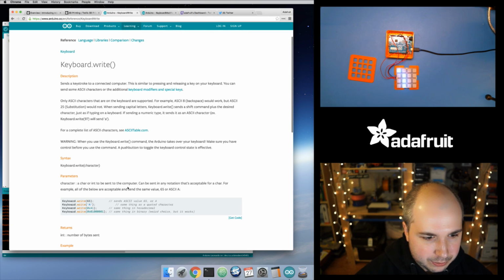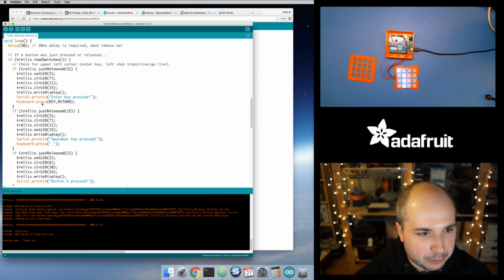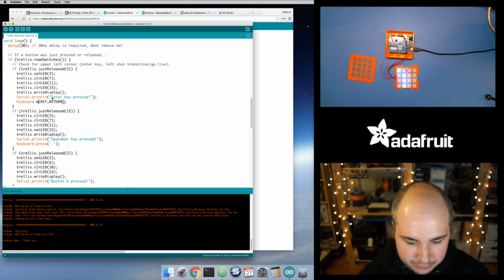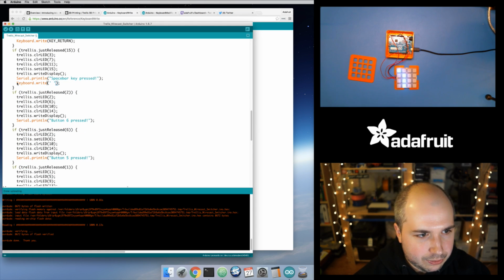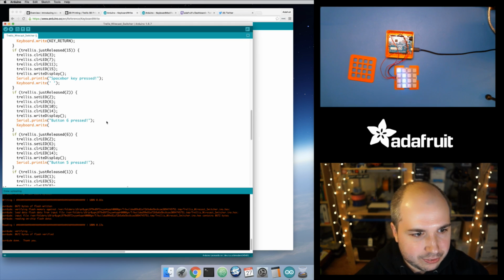Okay, so let's try this then. Let's do keyboard.write instead of keyboard.press. So let's do keyboard.press return. Let's do keyboard.write, and let's do keyboard.write for this. And let's go in and do this for all of these. Then to test this, I'll open up a text editor. Because I'm only using number keys, enter, and spacebar, I can basically type in numbers with this. So this should send the number 6.